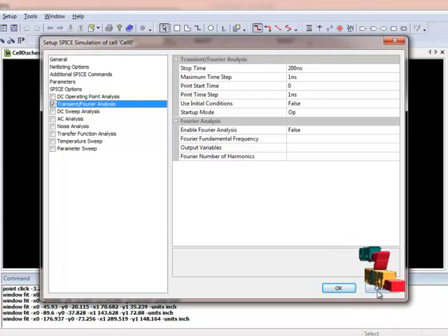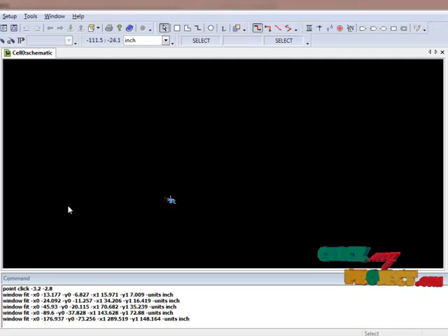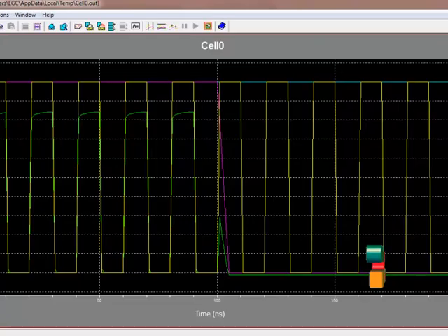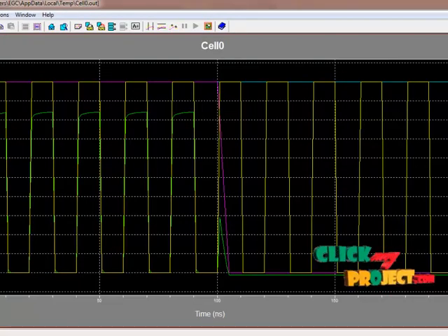After that we run the process. This setup is already completed. After we start the simulation process, we run it and open the T-Spice and W-Edit waveform process. In the W-Edit waveform process we get the waveform generation of the input and output, and T-Spice is used for the power calculation process. So we got the output from the W-Edit waveform viewer.